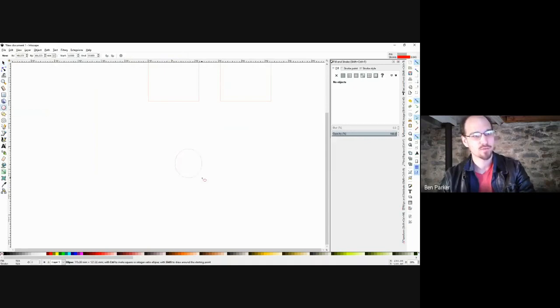You can draw without pressing any keys, and it might turn into an ellipse. You can hold the Shift key down, and it's going to expand from a single point wherever you started that. You can hold the Control key down, and it snaps it to being a circle. And you can hold the Shift and the Control key down to keep it as a circle from a particular point.